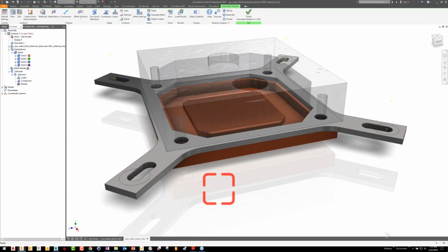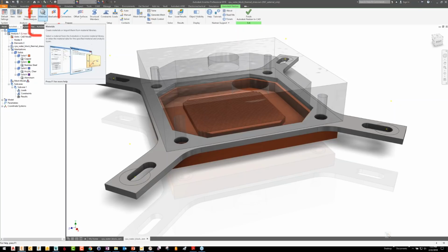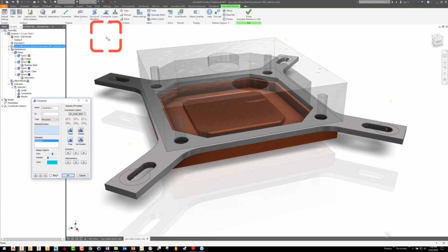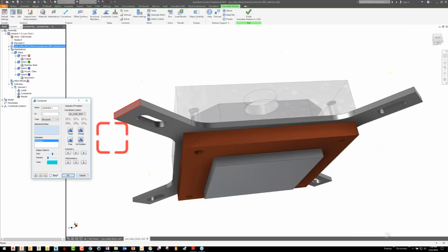And it's going to do the same thing. It's going to create for me my first analysis of linear static. It's also going to create idealizations for each one of the parts I have because they're all made of different materials. So that's a good 2 or 3 steps or more done for me already. It's detected the materials I had assigned in CAD, assigned those into the idealizations for me. So again, I'm a good deal along the way towards getting some results already. Now I'm still going to keep it simple and build complexity as I go. So before I get too fancy, let's just add a constraint, leaving it fixed. I'm not going to play with anything in there just yet.